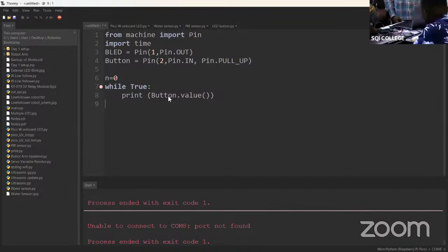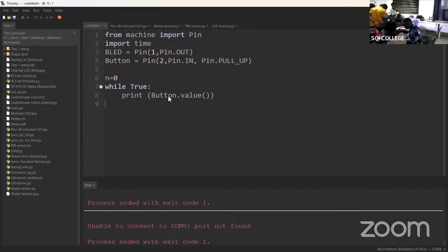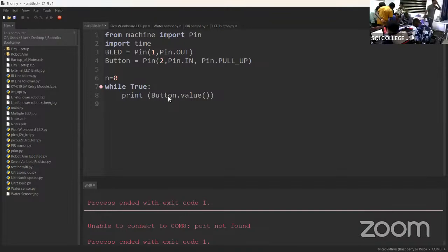This guy is connected, so I can connect my ground the same way. You can now pick another GPIO pin for your positive side of your leg and make sure that your ground is also connected. Another GPIO pin. Pick anything you want. You pick 21. Then here's the ground. Yeah, that is ground. Okay. Have we all gotten our circuits correctly?